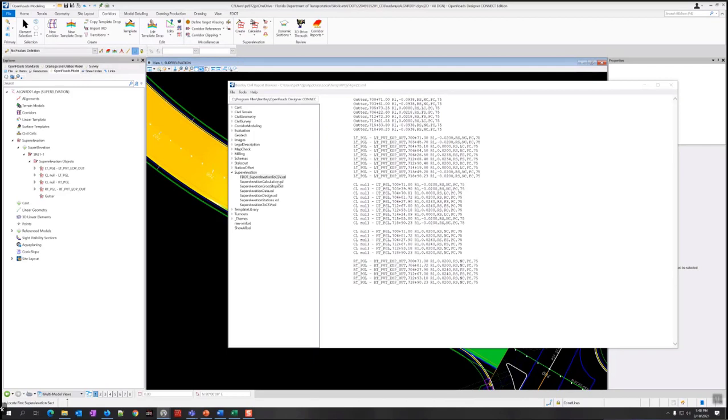And let's see. So this one looks okay. The formatting still looks okay. So here's where we get that 4 decimal points for linear. This is actually our cross slope, but we want to make sure we keep this 4 decimal points. It cannot be in a percent here. It won't import correctly if it is, so it's got to be in this decimal format. You can see the station. You see the lane. This is all just comma separated. This is the RS for...